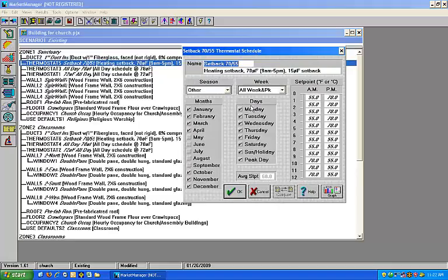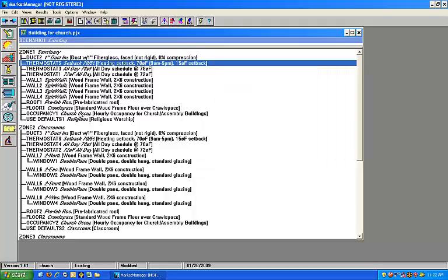So a thermostat schedule is at what temperature do you want your zone at? And here it has a setback, so it looks like it's 50 degrees, 55 all night, and then they will bring it back. Let's see, this is winter, good. So they'll heat it to 70 from 9 o'clock until 5 o'clock, and then they'll let it drift back down to 55. Okay, that's not so bad.